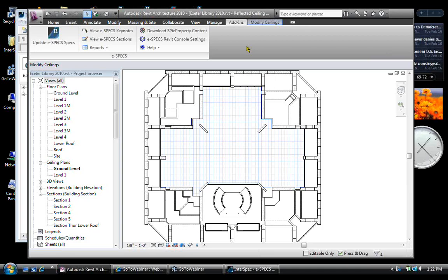So if I look at Omniclass to really define that window, I may need more than one to correctly define that complete assembly. In this example, I would probably set the Uniformat classification to wood windows, and then use Omniclass to determine the type, the double hung, the casement, and that sort of thing. So those two things in tandem can really help me define that product pretty well. In addition, I might have additional parameters that identify the finish on the window, the glazing type, and that sort of thing.